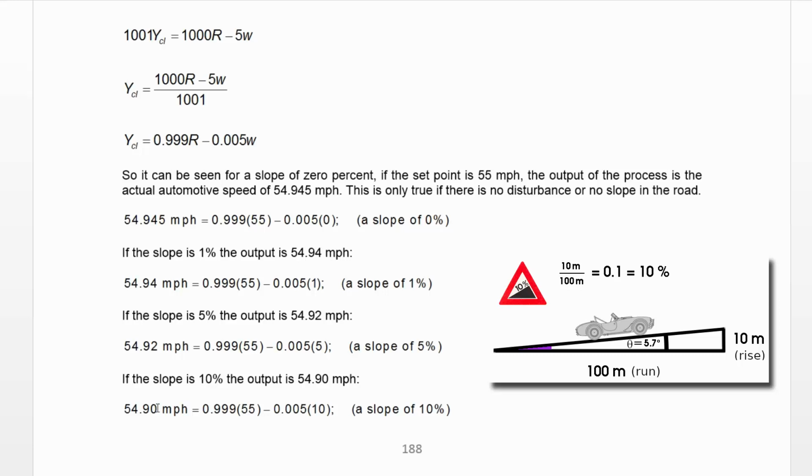Now, to correct for these errors, we can add integral mode. If we integrate the error in time, that would be E times T, error times time, times 1 over the time in minutes. So right now we have cycles per minute, which is 1 over minutes. You take the reciprocal and you get frequency of time. So the reciprocal of time is frequency, and frequency, in this case, would be cycles per minute, and typically our inputs are either repeats per minute or minutes per repeat.